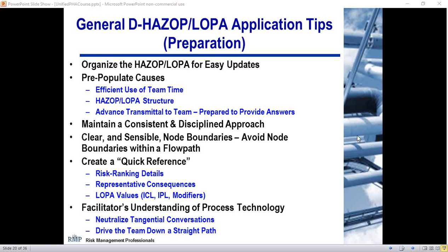The reality is we typically recommend selective application of LOPA as you're developing the HAZOP scenarios. If it's important enough from a consequence or risk perspective, LOPA can provide insights. Perhaps you're overestimating the risk.